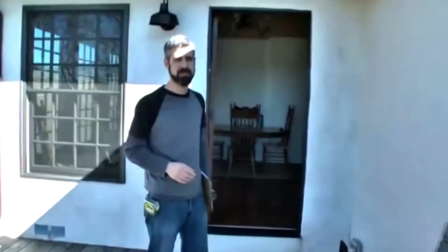So if I'm going to do a blower door on a house, the first thing I like to do is to get a feel for the house. We also want to go around and look for things that are open. Any door or window that's open to the outside, we want to close that before we start the blower door test. And in that same vein, anything that's open on the inside, interior doors and things like that, we want to make sure that those are open so the air is flowing through the entire house.